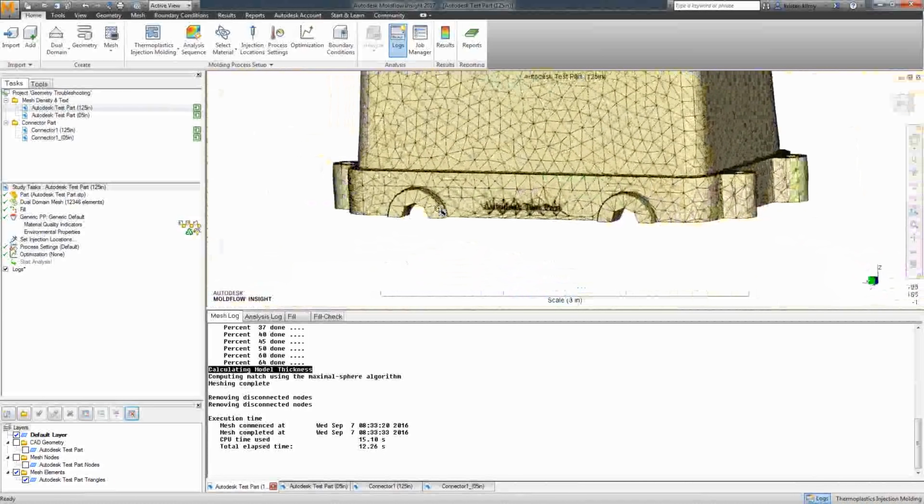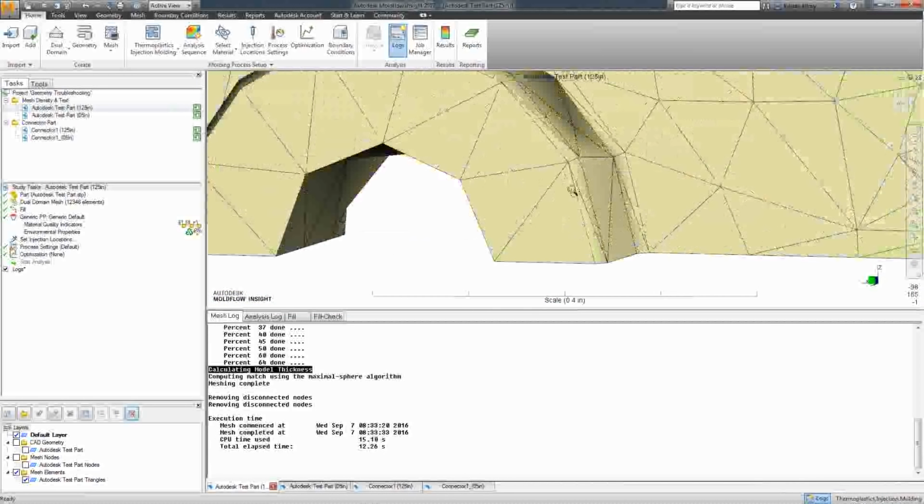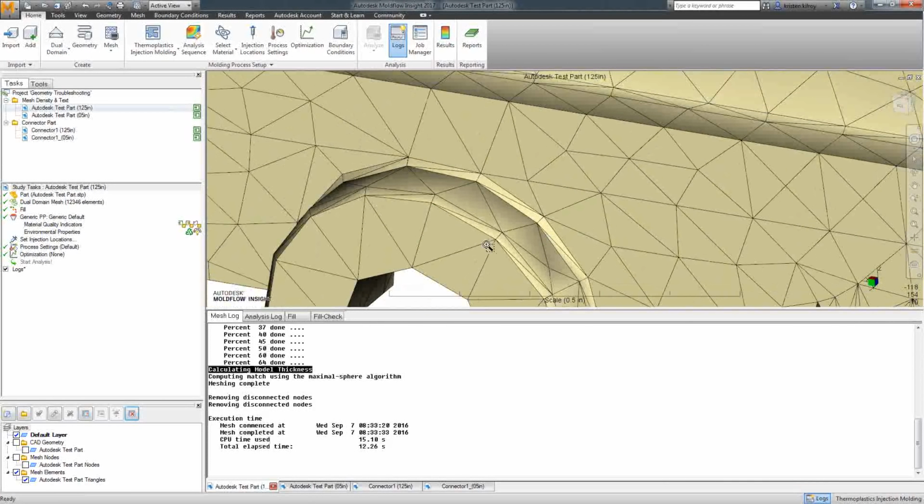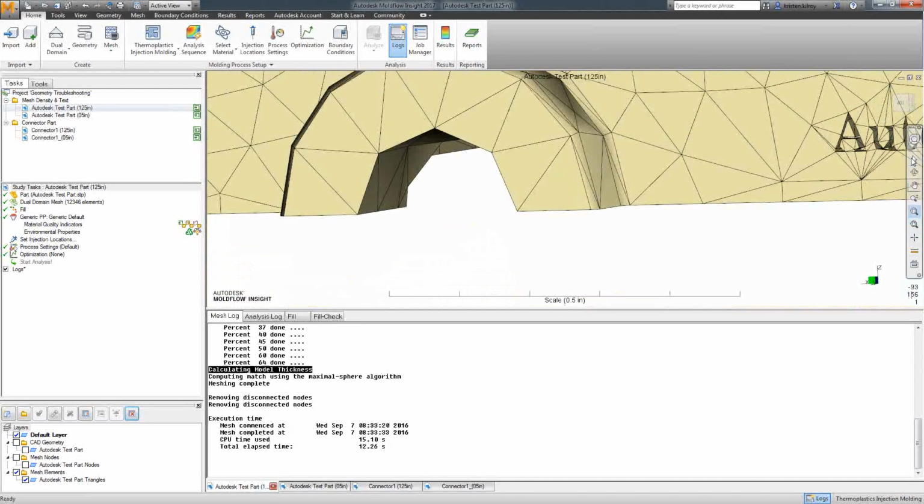And same thing with those fillets and so forth. Here we've got some fillets. They don't look like they'd be too alarming for aspect ratio, but you might come into situations where you're using a much larger mesh, so it's really stretching that element out, and that would be a real pain to go in and manually fix all of these. So it might be better to eliminate those fillets altogether because they're really not adding too much to the flow calculation.